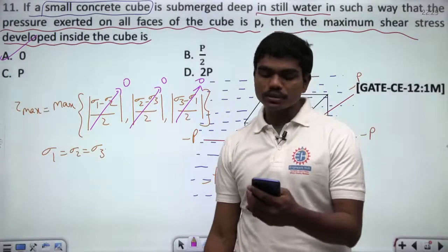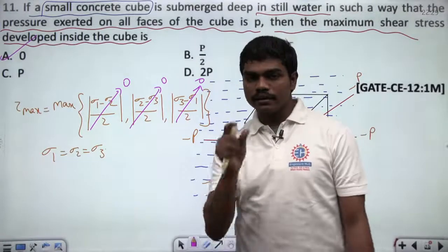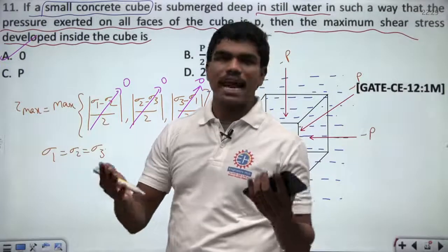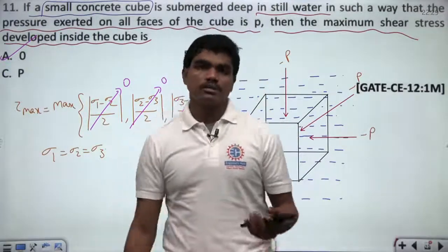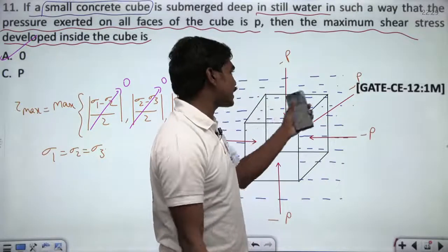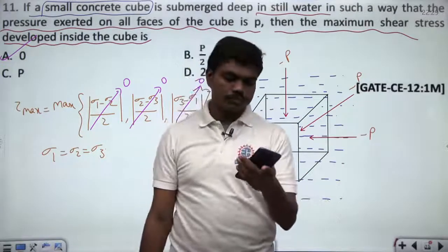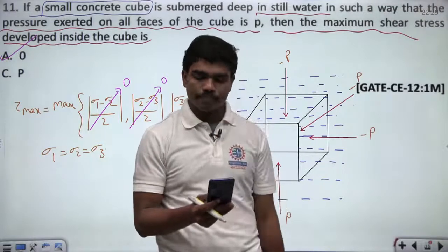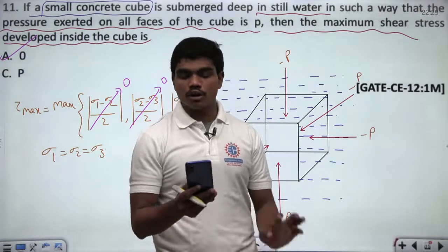Please do type in the chat box. Because the complete fluid is static and the cube is so small, if the complete fluid is static, then there won't be any shear stress acting at any point in the static fluid. Similarly, there is no shear stress acting at any point within this cube. So definitely the answer has to be 0. Fine. Okay, so shall I go for the next question?